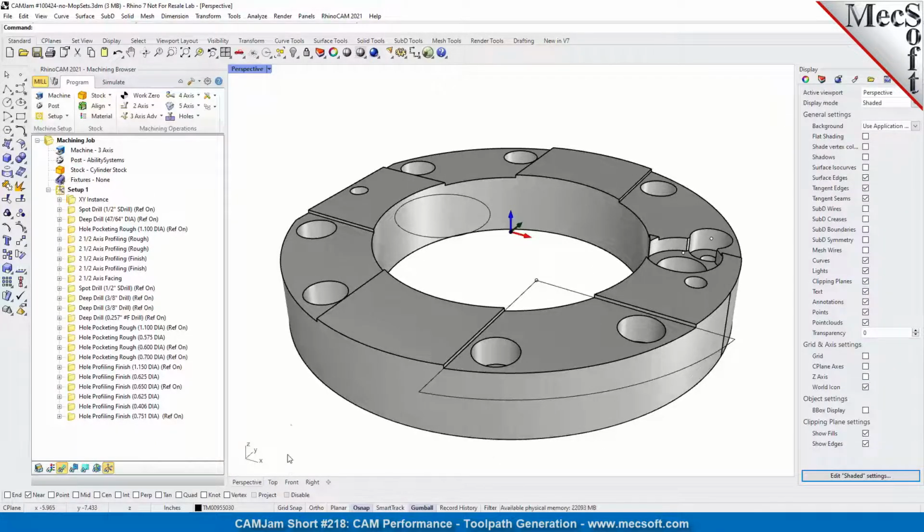Using the right tolerance is very application based, and you have to fine tune it and do a lot of experimentation yourself on the type of parts you're machining, the size of parts, the material, as well as the machine tool that you're using. There are a lot of factors that determine the sweet spot, if you will, for the operation tolerance.